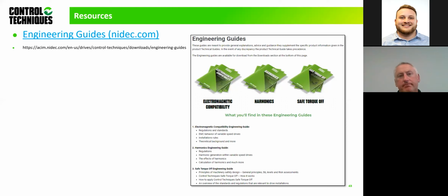It looks like someone's asking about where your slides pointed out that the point of common coupling is typically the low voltage side of the supply transformer. In what cases would it not be that location? If I'm a steel industry connected right next door to a suburban community, the point of common coupling would be at the MV. If you're disrupting, you've got a chance of disrupting that community. So you've got to be very careful with the point of common coupling.